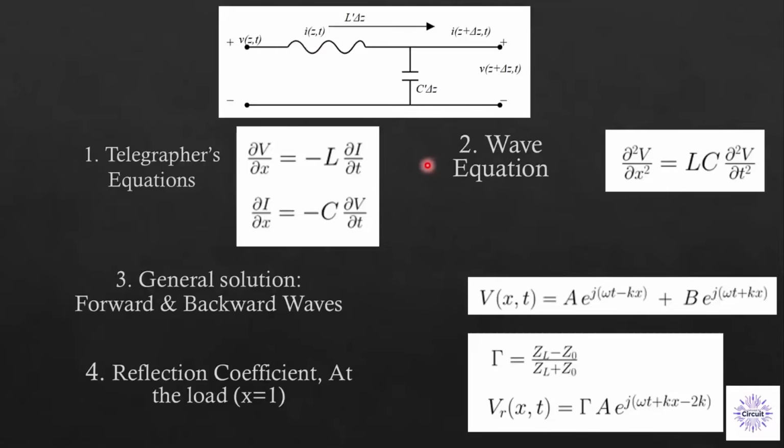And this effect doesn't allow us to use KVL, KCL, or the Kirchhoff equations that we usually use to calculate the voltages and currents in circuits. What we need to do is account for this short wavelength of the signals when they are high frequency, and account for what happens to their phase and their amplitude as they travel a distance. This is transmission line theory.